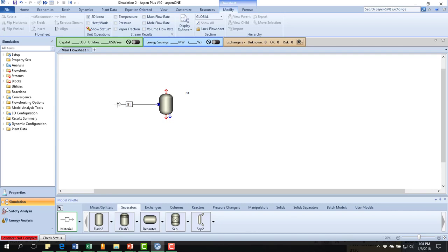Sometimes we miss. You can tell whether or not it's connected. If it's connected, there's a little black arrow that's just kind of a single line. And if it didn't connect, it's going to terminate in an arrow that looks like this big white block letter. So this one connected. I'm also going to add 2 product streams. And I'm going to not connect this one properly. So you'll see how this one, both ends of this are the white blocks.